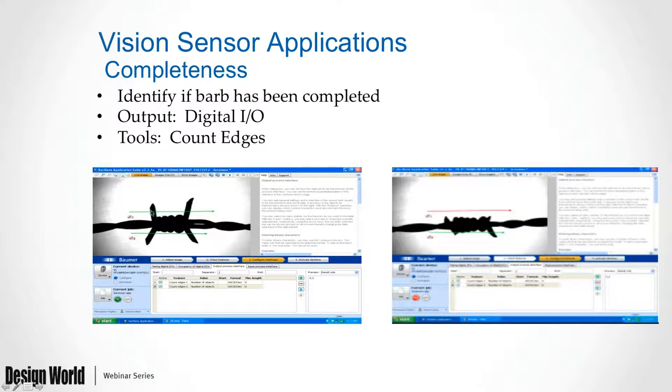In a case like this, I can look at transitions from bright pixels to dark pixels, and the same thing on a duplicate tool on the bottom. Ideally, I should see 2 transitions. On the right-hand side, if I have some things missing, actually no transitions on the top one completely, then we've got an error, and we can put a digital output to that.